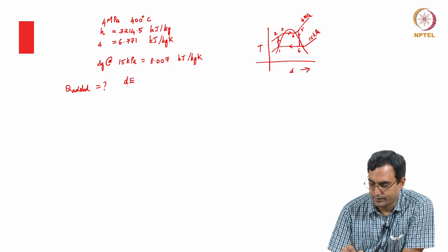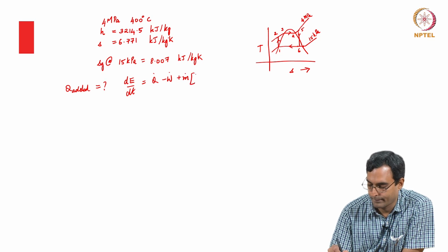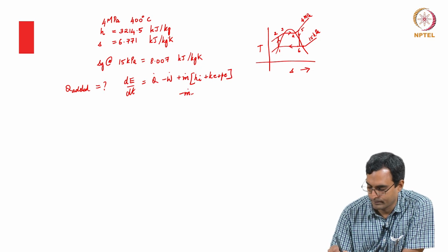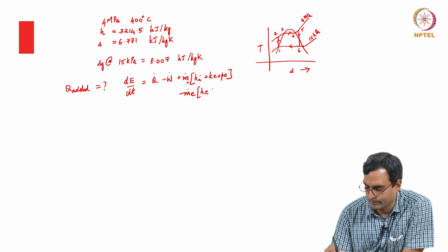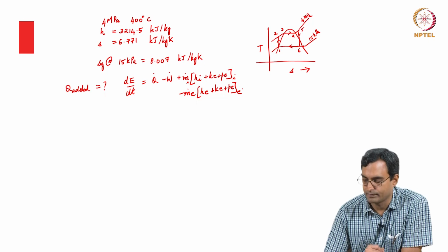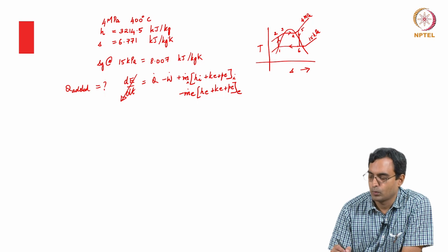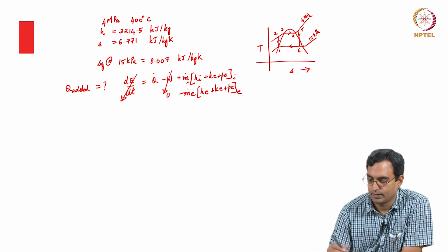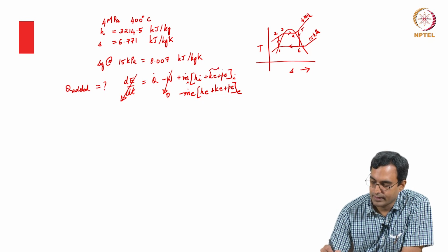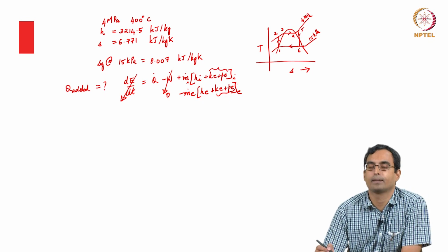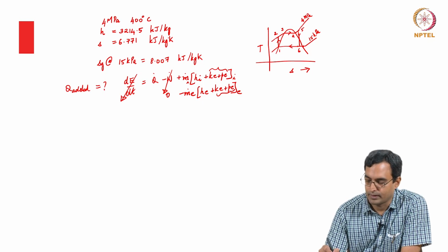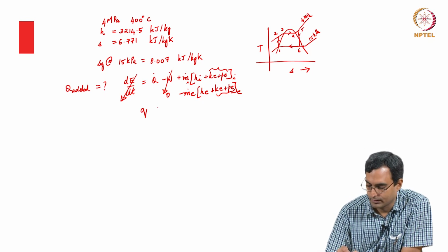From the first law for this process, we have this. This is generally expected to be steady state. So, this is 0. There is no work done in the heat exchanger. This is 0. Changes in potential and kinetic energy are usually negligible, and I do not know anything about the velocities, so I will assume that this is 0, which then gives me Q.